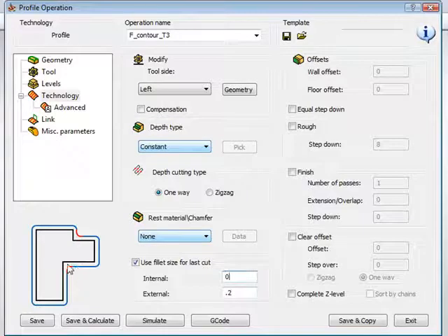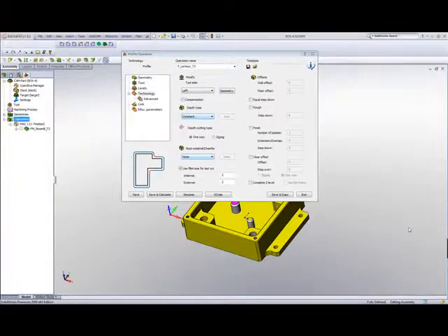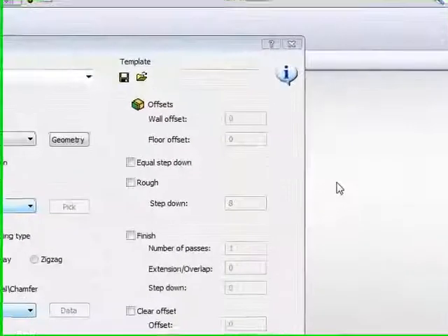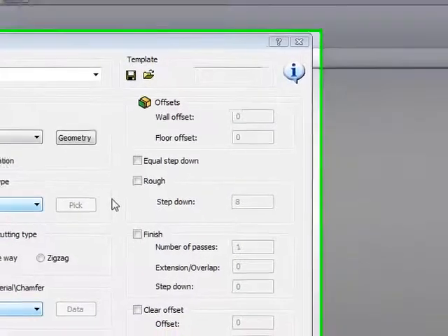If my tool radius is the same size as my radius over here, or larger, especially when you have a sharp corner, so every tool is larger, it'll create the center tool path with a slight radius, thereby not putting extra pressure on this wall over here. So I can put, if I need, say 0.2 millimeters as well. We'll now move over to the right hand side of our screen.